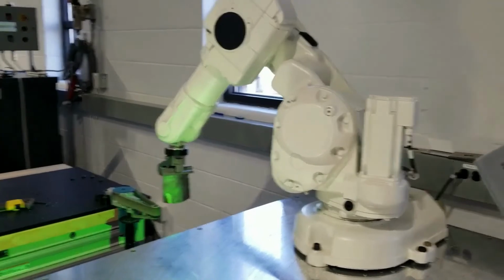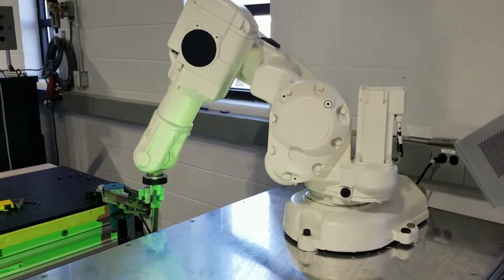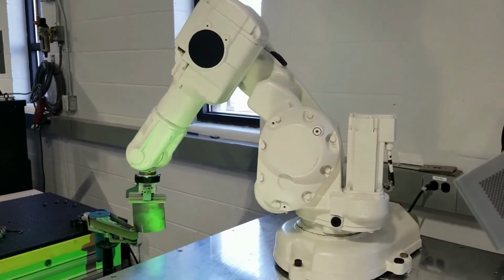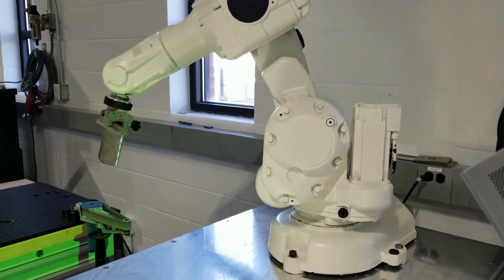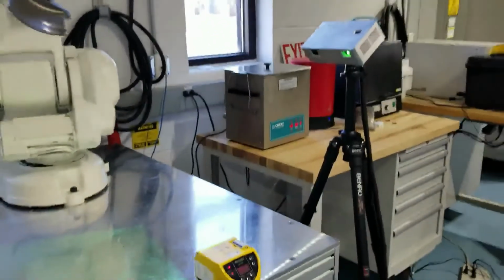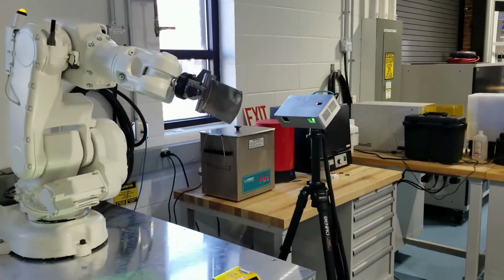And if I can jump in here too, when the program runs, each time it iterates, it sends and gets the result that the part is not good. It steps the tool in closer to the sander by a predetermined amount that I set ahead of time.